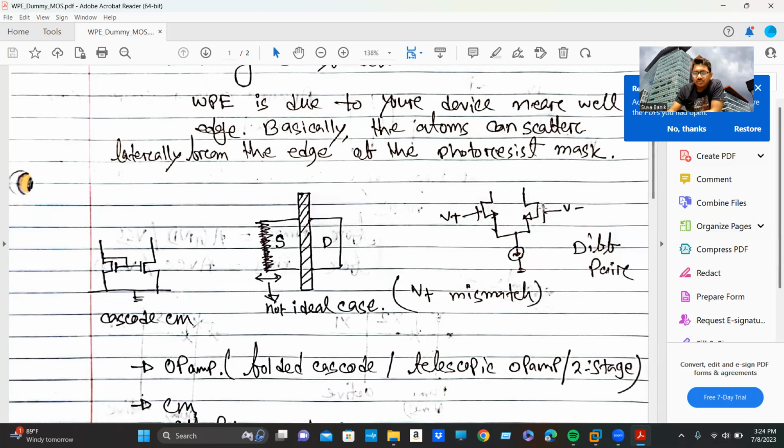After doing the layout, they surely do not get the effective gain, the phase margin, the current limit, everything whatever they calculated, for example in the corner process, so they will lose their performance. Basically, they lose their circuit performance.